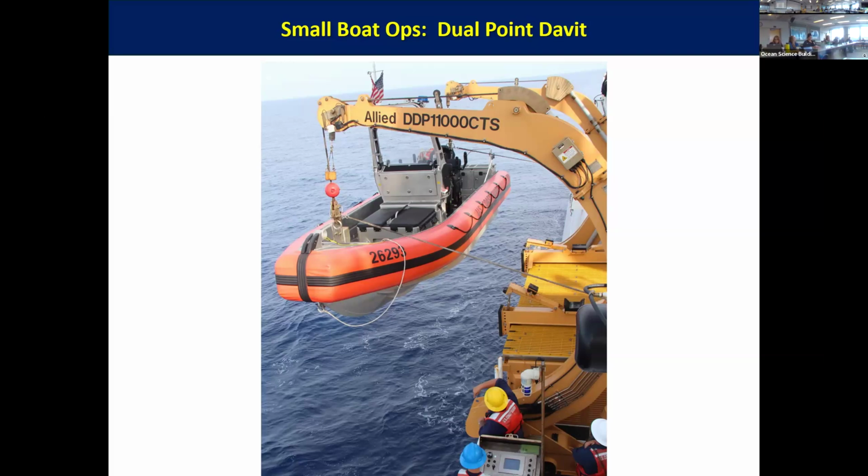Now, I don't want to go straight into the seas because in a minute, I'm going to put that boat in the water. I don't want a ton of swells coming down the side. So there's a sweet spot. I put the weather off the port bow for the wind and seas. It's similar to doing helicopter operations. So depending on which way the wind and seas are, so I can get them off my port bow, that's the direction I've got to go to get this boat down.